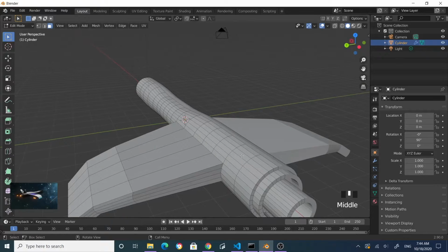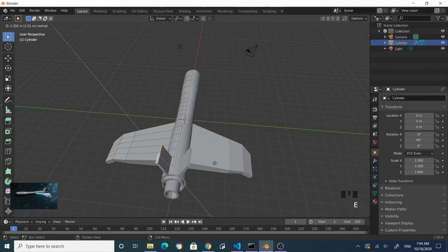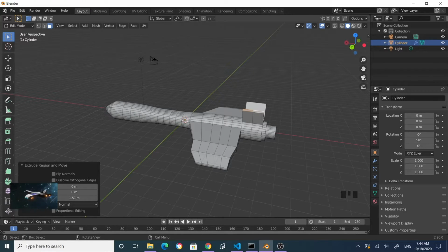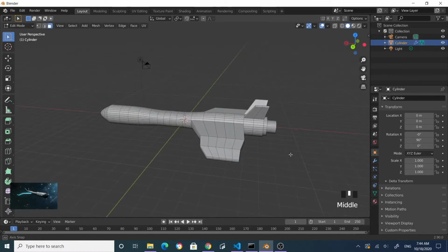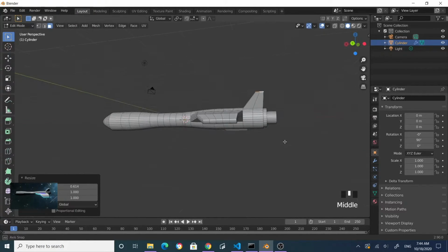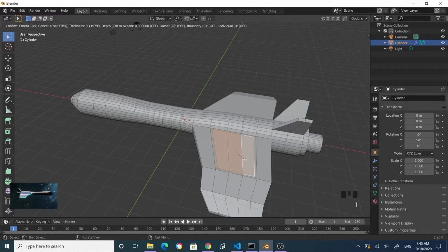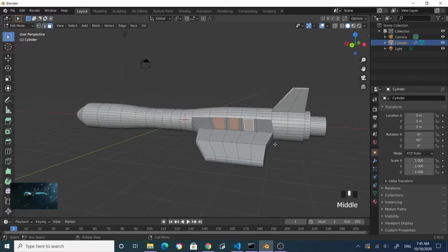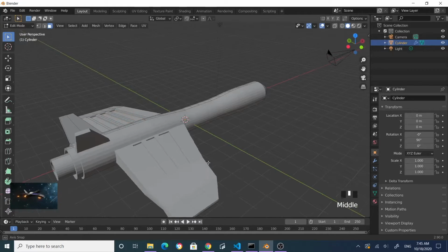Now let's build some wings here. Select this and also shift select this, and then extrude. Now scale along x-axis, S and X, then G and X. Let's scale this down slightly. Scale X. That should do it. All right. Let's select this face, and this one, and then press I to insert, I again to do individual faces. Now select these faces and then extrude inward, E. That gives some kind of like a nice grid-like pattern.